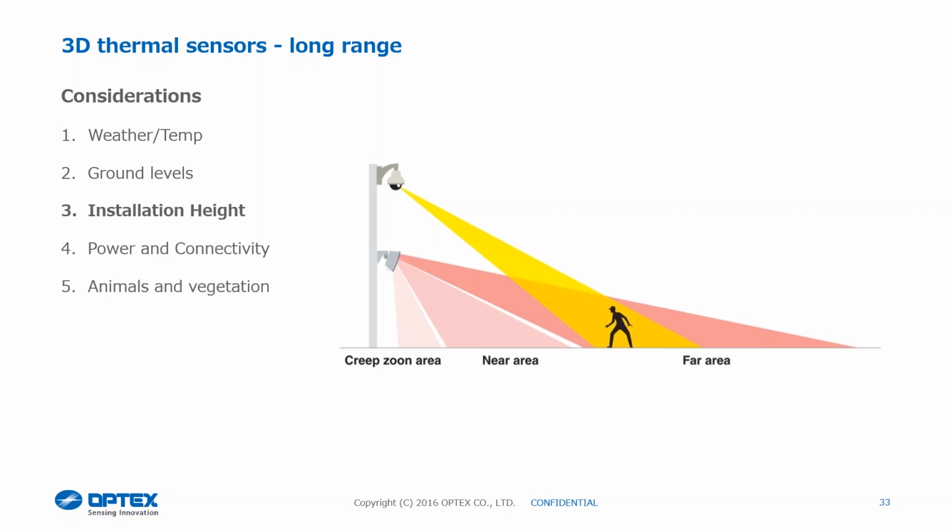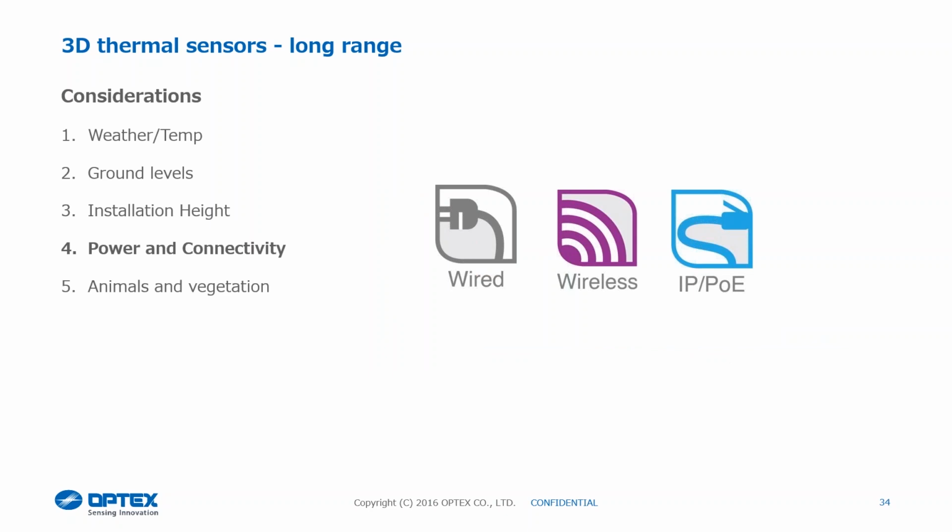Moving on to the power and the connectivity, again, we can do the hardwired version, so the full range of SIPs are available in hardwired and also the PoE version. And the shorter range products, so the 3020, the 4010 and the 40x4, are also available in wire-free versions. That's ideal for a site that might have an installation on it and you go back sometime later, they want to add an additional detector, but it's over the other side of the tarmac compound that's out the back of the site. So rather than doing a lot of civil works and digging that up, we actually do wire-free transmission. You can install that detector in the location that it needs to go in and then just use that wire-free transmission to get that back to the site and hook it into the existing CCTV system.